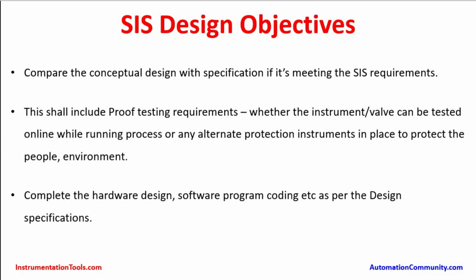So in this case, the design will be developed by one company, like an engineering, procurement and construction contractor, whereas the installation and other parts will be done by a different operating company. So there may be some gap. Whenever the design is developed, the instruments are implemented and bought, it has to be ensured that they meet the conceptual design requirements.